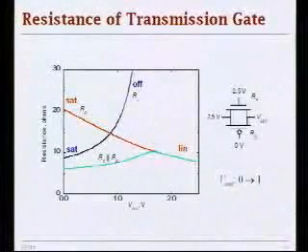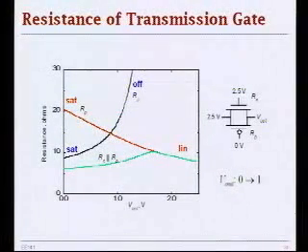And notice in the slides, one good thing about putting those two transistors in parallel is that the total resistance you see is approximately a constant, which makes it easier to predict the behavior of your circuit. The less nonlinearity, the simpler the equations we have. So, any questions?